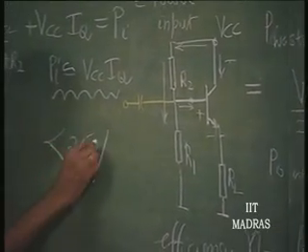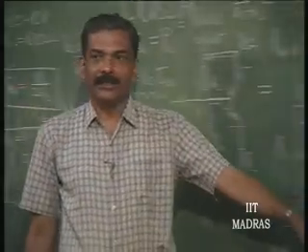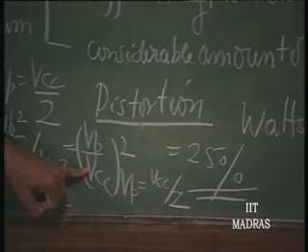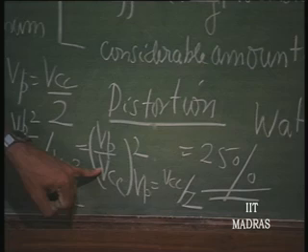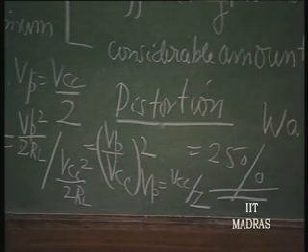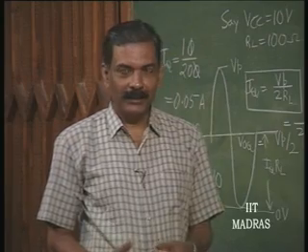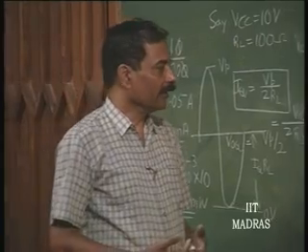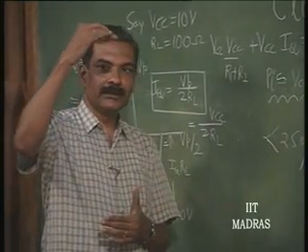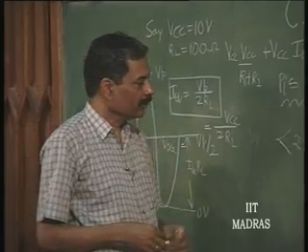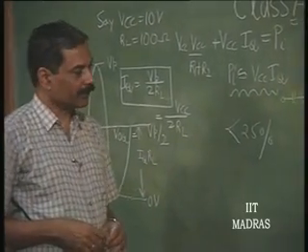25%, because this is only the best efficiency possible, and it is not possible for us to have the signal always at V p. The signal is going to keep changing depending upon your output. So, this is maybe an audio signal. At best it can reach V p at a certain given moment, that is all. So, this is always less than 25%.